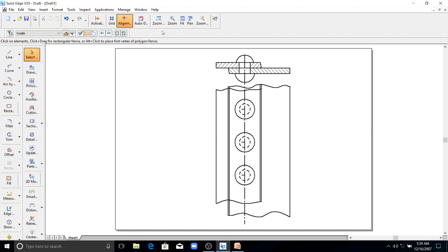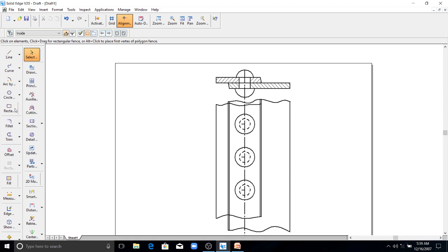So now you can give the dimensions. This dimension is from center of the rivet to the end of the edge of the plate, that is 27 mm, 1.5D. So the thickness of the plates is 9 mm. This is 9 mm.